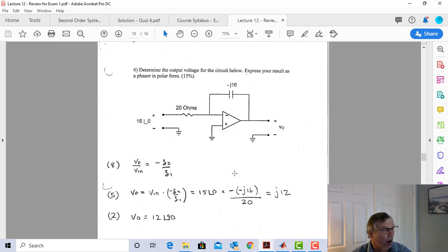But for now, make sure that whenever you look at an op-amp circuit, that output feeds back to the negative input. That'll save you in lab classes when you hook them up backwards and it doesn't work, and it might save you in a job interview too, because if you want to know if anybody knows anything about op-amps, just connect the feedback to the wrong terminal and see if they catch it.